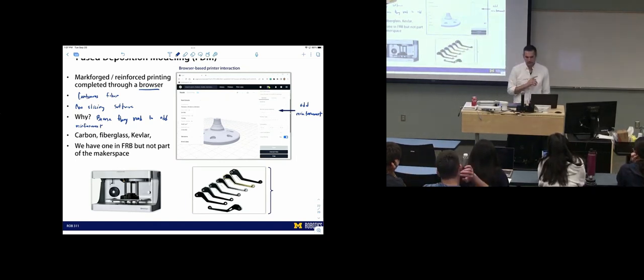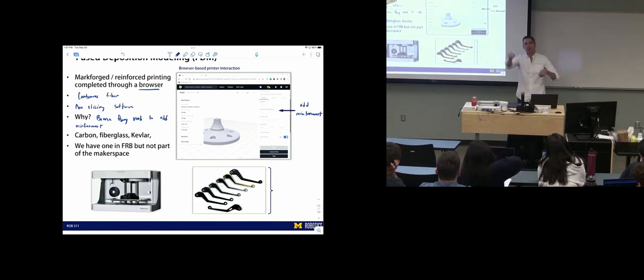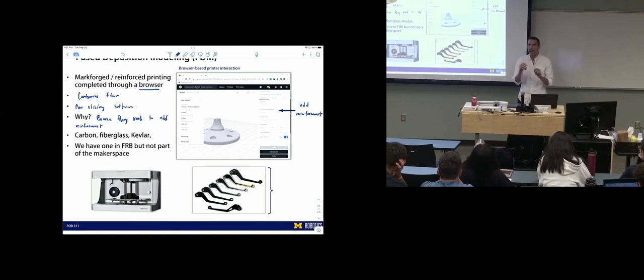Do you want to briefly explain again what you mean by the continuous fiber? It means as it's printing layer by layer, it's got G-code giving it its instructions, it knows what material to feed. That's regular FDM printing. The Markforged has another capability: in addition to printing support material and build material, you can also feed a long, spooled piece of fiber. It mixes the plastic with the fiber, and the fiber can help distribute loads, just like rebar in concrete.